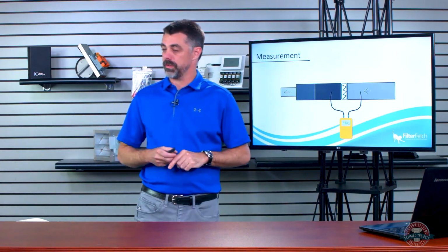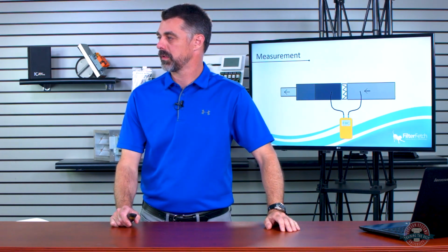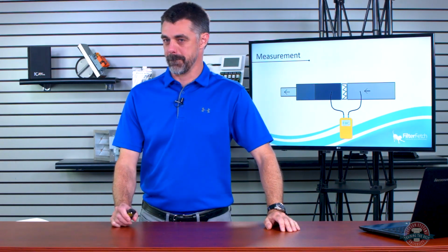Eric, I got a quick question for you. Yes, sir, JD. What Ricardo wants to know is what Merv rating do electronic air cleaners belong to? That depends on how clean it is, and it depends on the electronic air cleaner. I don't think they typically fall under the Merv rating. Some might have a Merv rating on them. The challenge I find with electronic air cleaners is that they get worse filtration the dirtier they get. So they start out clean, and their filtration efficiency tapers down as they get dirtier.